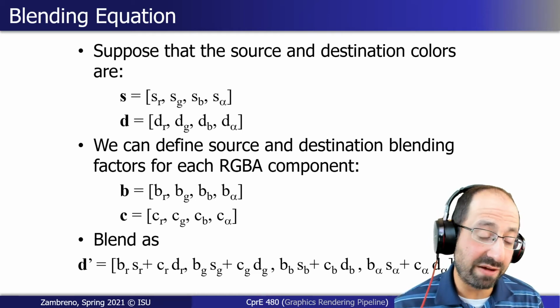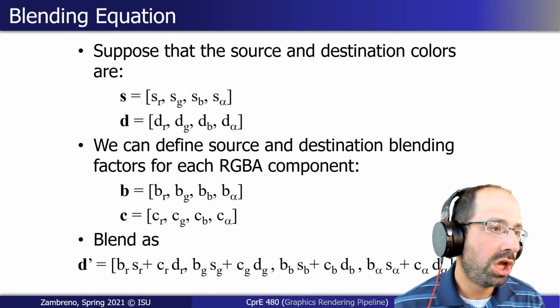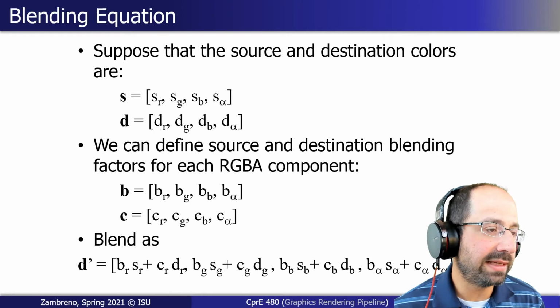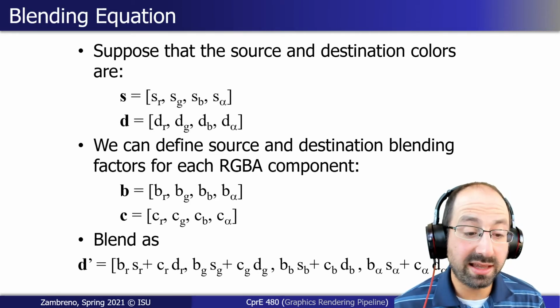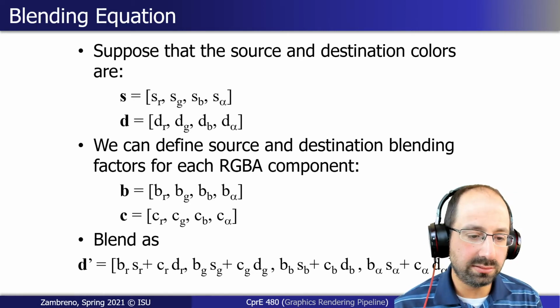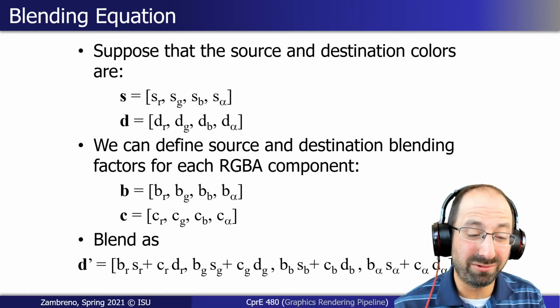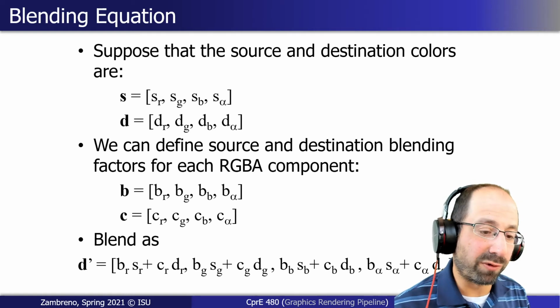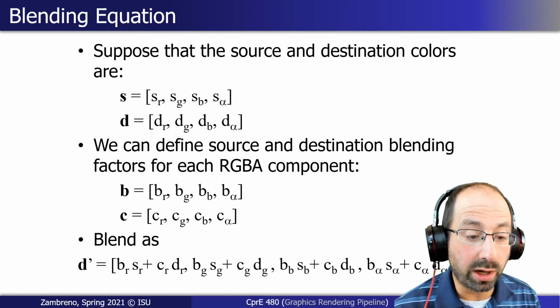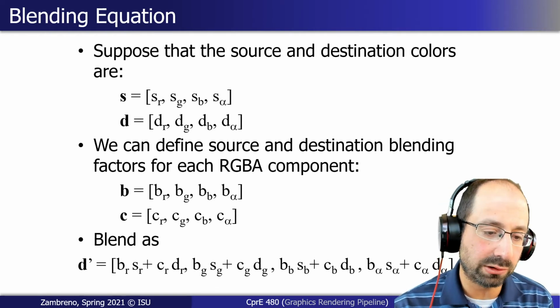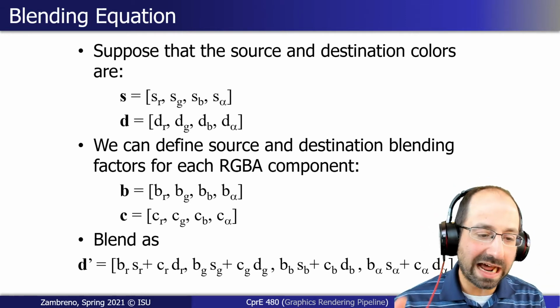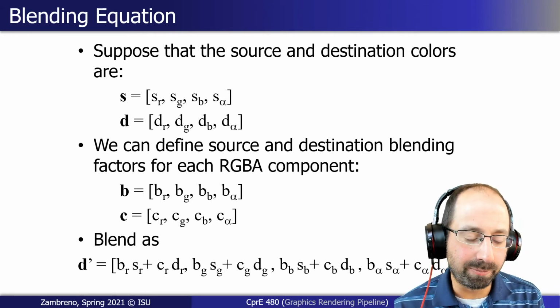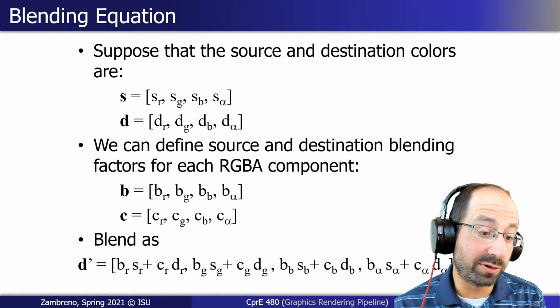We are going to be storing it just like our color channels, just for simplicity's sake, if nothing else. We've been storing our color as these Q16.16, but I think those who really dived into the driver should realize we really don't need that, right? If we're forcing them to be between 0 and 1, or we're assuming they're floats between 0 and 1, then a Q1.31 format would maybe make more sense for storing it.